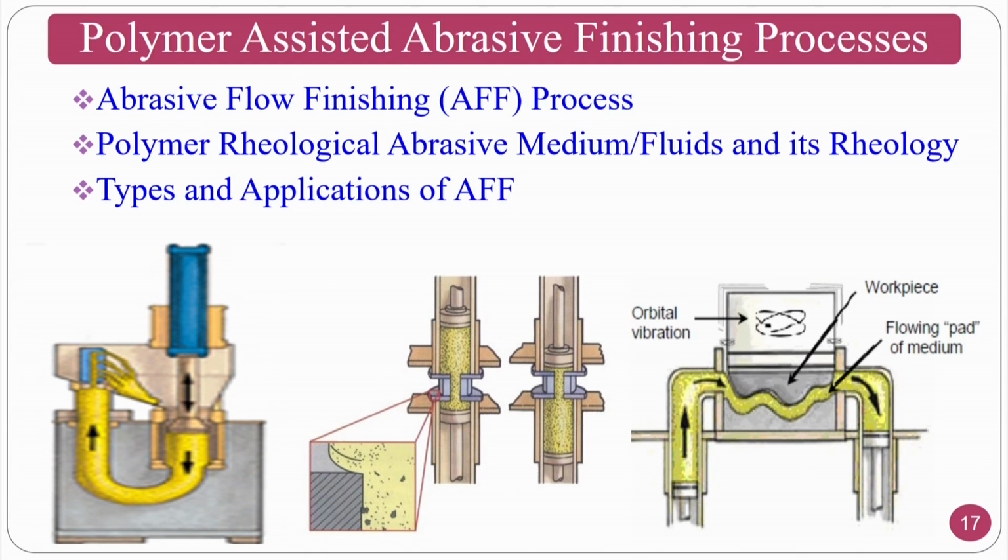If you have a knee implant, it is very difficult for a magnetorheological finishing process to finish. If at all we want to finish, the basic problem is the finishing time will be very high, because you have an electromagnet and the electromagnet distance is constant, because of which the field strength will be varying for the continuous curvature of the knee implant.